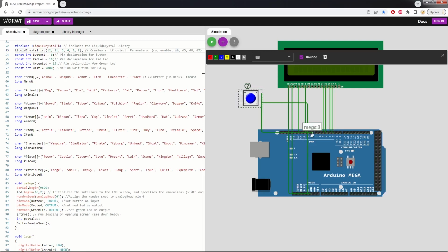So when the pin 8 is high, it just triggers. I'll put it that way so it's easier to understand. And in my design as well, I put a 100 kilo ohm pull-down resistor, which helps to avoid the fake high and the fake low.